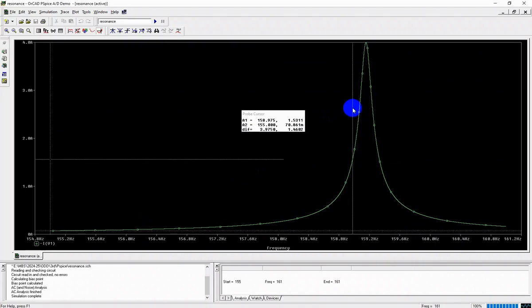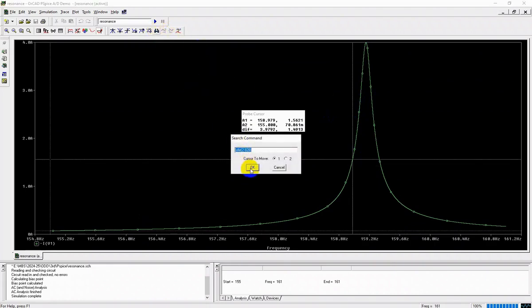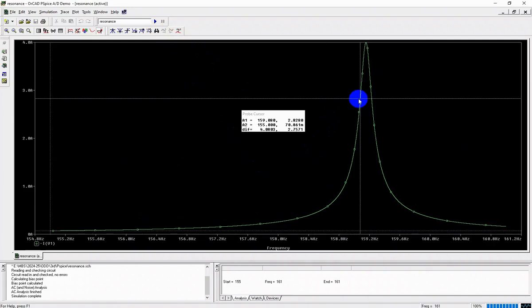The line for 2.828 cuts the curve at two different points. This one is F2, and the first point where it touches the curve is F1. Since we want A1 to land here for F2, I type the code again and say OK. It moves to F2. You can see A1 is at F2.